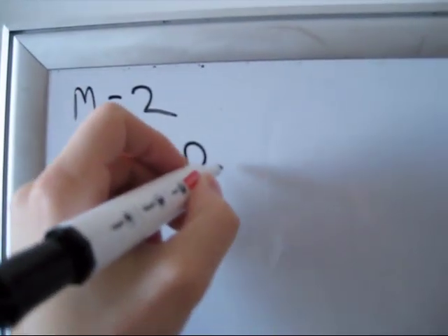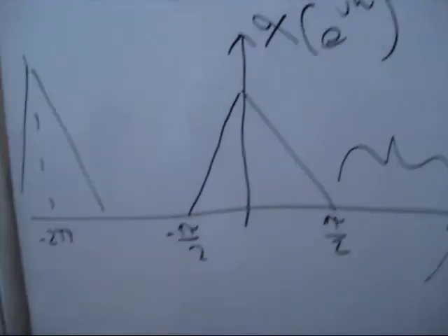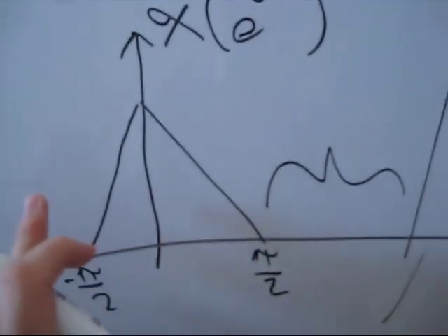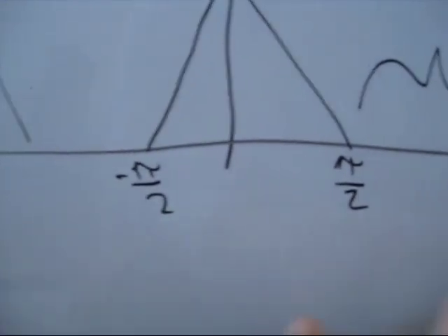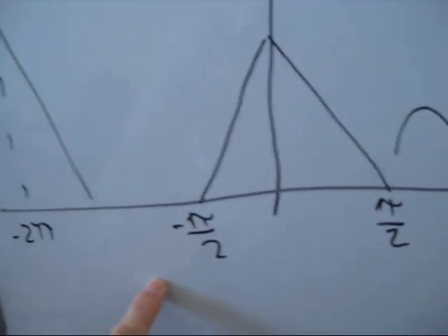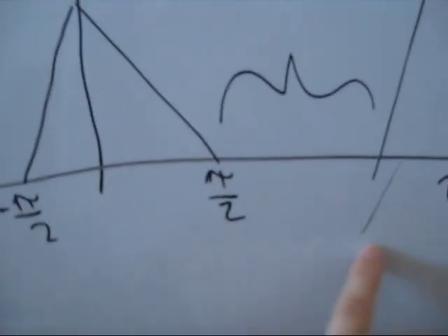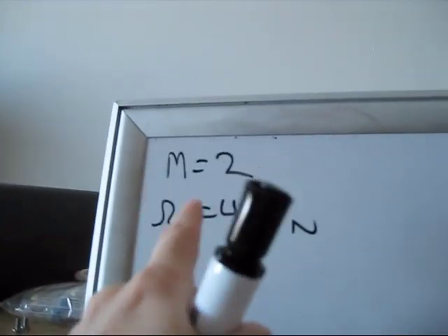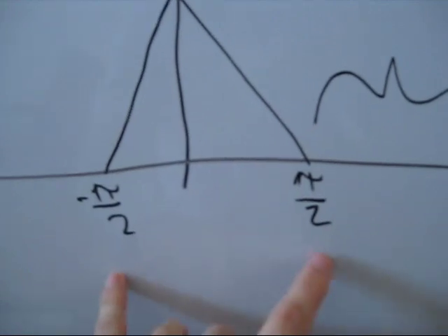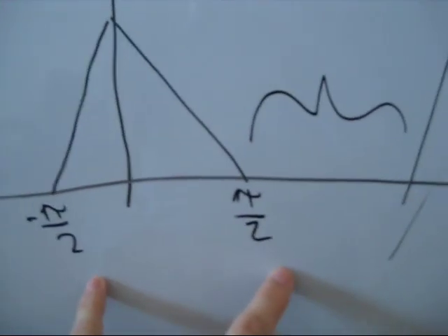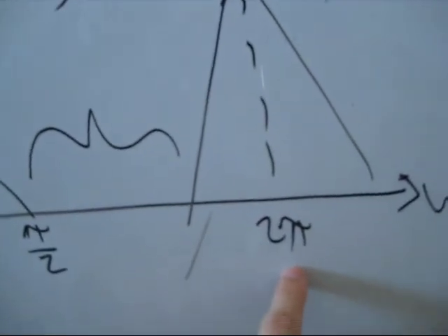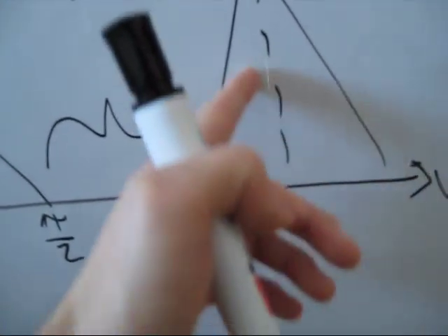I'm just going to write down our original givens here. What you do is you look at the graph and you multiply everything down here by m. In our case, if we're downsampling by 2, m equals 2, we're going to multiply where these lines end by 2. Technically, you actually multiply everything by 2, including where the replicas are.